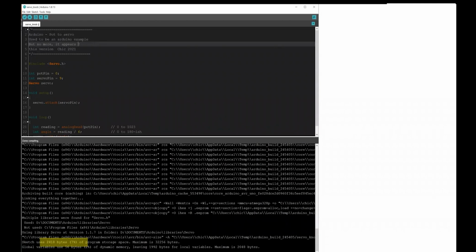However, it's not hard to write. It takes 7% of the Atmega 328 to put a simple servo like this in. And it uses your only timer. And it's blocking. While it's doing the servo, it can't be doing anything else.